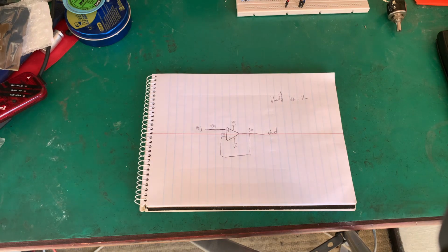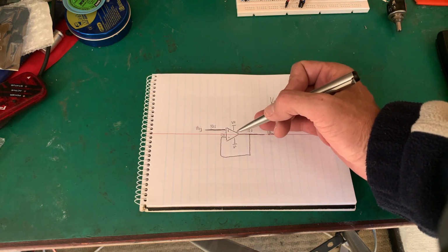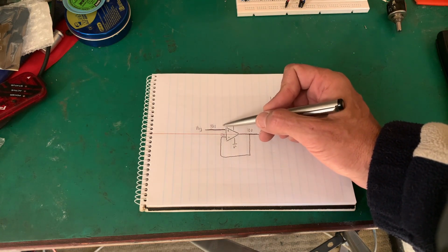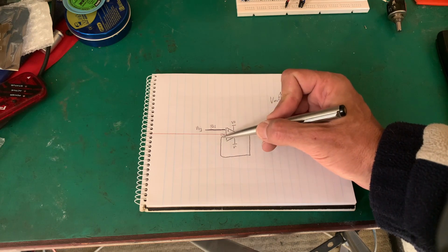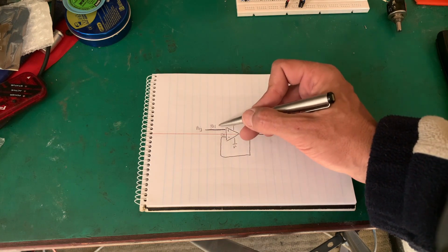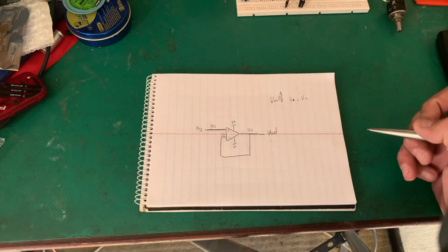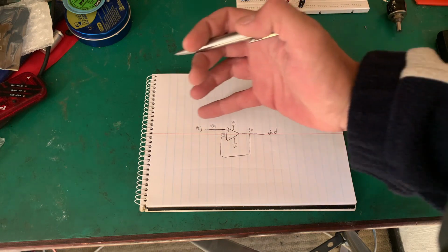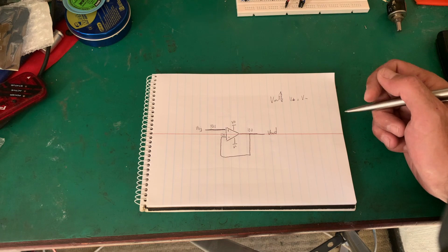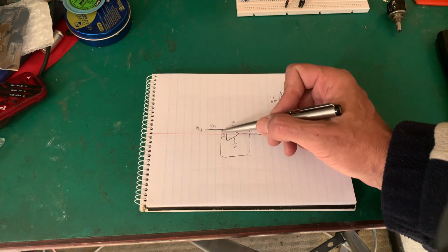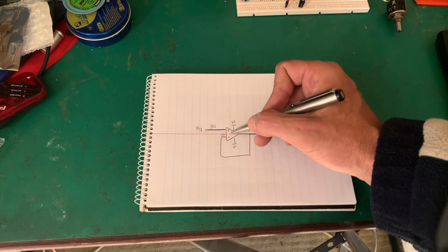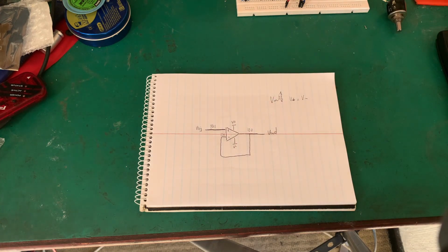Well, this is known as a simple voltage follower, but if we remember, we said these inputs have infinite impedance. What does that mean? No current flows in here. So this makes a good isolation piece. So now I wanted to isolate two parts of my circuit, two different supplies or something like that. I could use this voltage follower, or as it's more commonly known, a buffer. Very important use of op-amps.